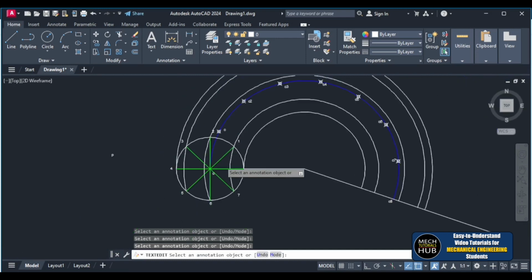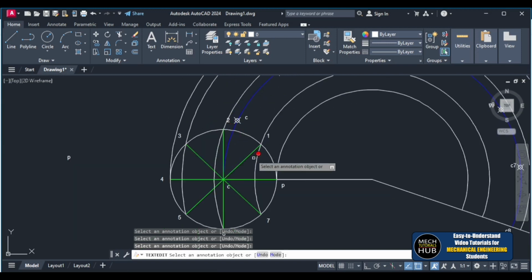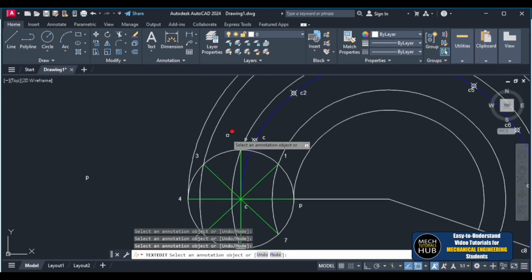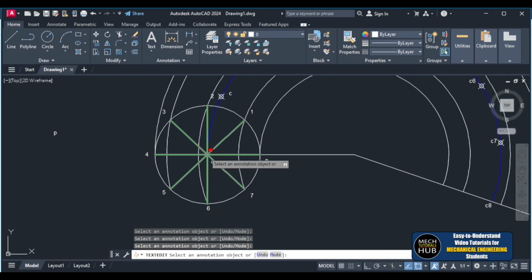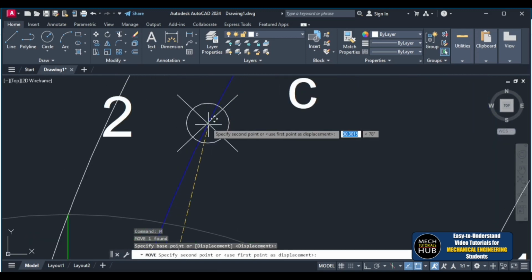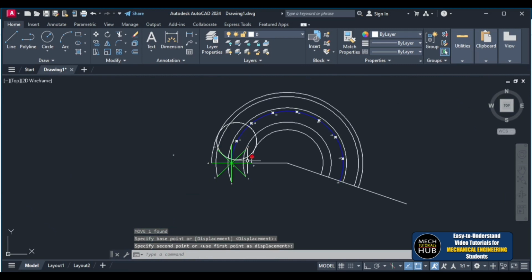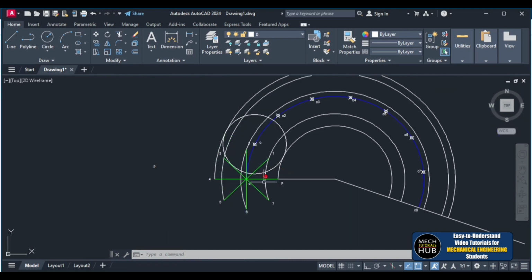Alright, so what is our discussion? When the circle starts rotating with respect to this reference point, the reference point will make a number of instances or intersections. That we'll try to see now. When the circle changes its position or changes its center from C to C1, what happens? Select the circle, move, enter, and hold the midpoint of the circle. Then I say place it at C1. Okay, place it at C1.